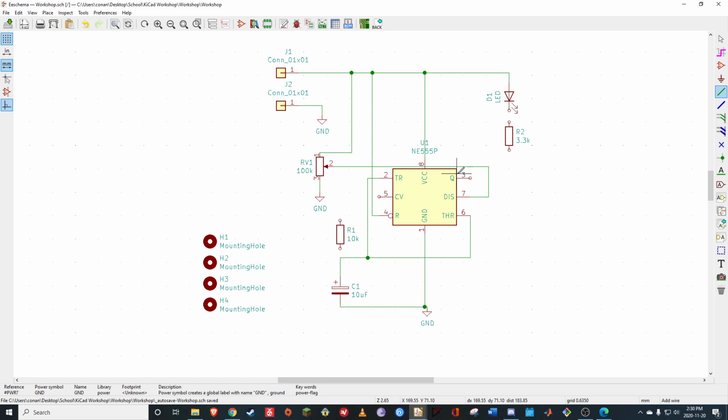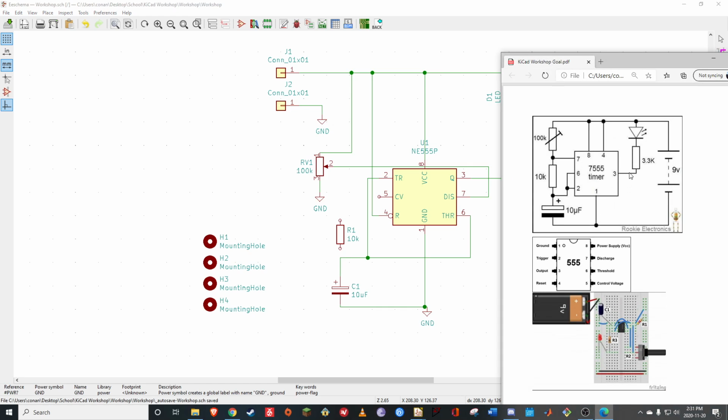Okay. Now we just need to figure out where pin 3 goes and what pin 5 is doing. We could also connect these. Now, I already know that pin 3 is our output. That's what Q means here. So we know that whatever this timer is doing, the signal that it supplies needs to go into the resistor to apply current to control into the LED. Let's make sure that I'm right. Okay, pin 3 just goes in.